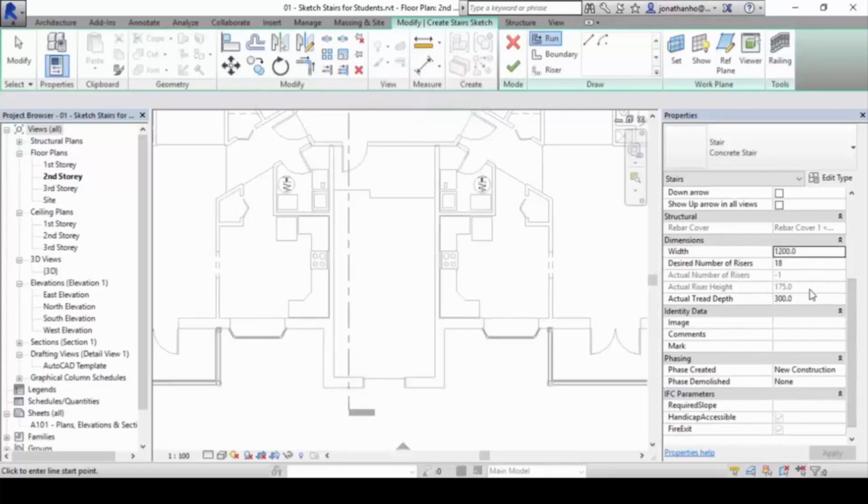Now our highest allowable riser height remains at 175 mm. We are not likely to grow genetically anytime soon. Okay, so we are not likely to grow by another 200 if not 300 mm taller. So therefore the riser height should not change very much. It should remain this. In fact it will drop given our aging population.